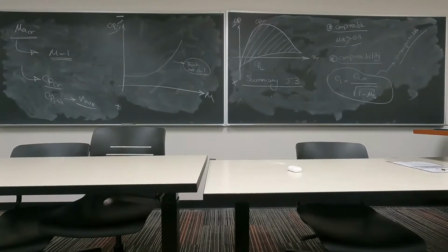So we are actually talking about the relationship between pressure and the Mach number. So that angle theta doesn't really play a huge role here, right? But think about it this way. Think about the perturbations. A thick airfoil is going to cause a perturbation in a flow versus a thin airfoil. A perturbation a thin airfoil is going to cause is going to be less, right?